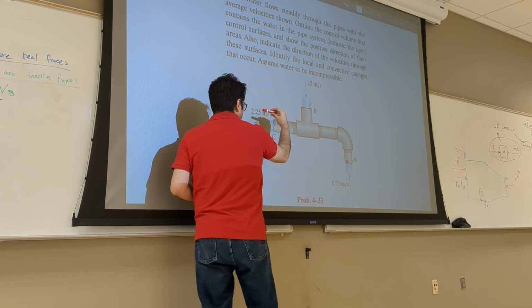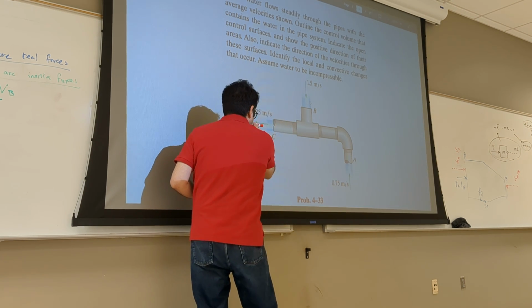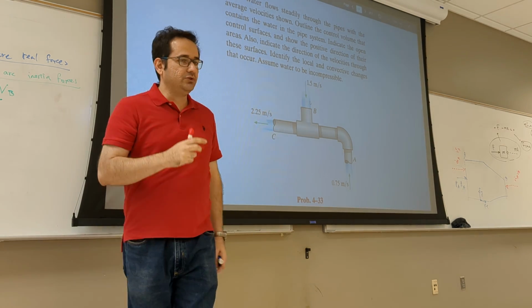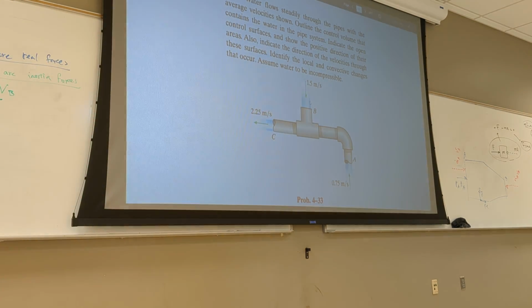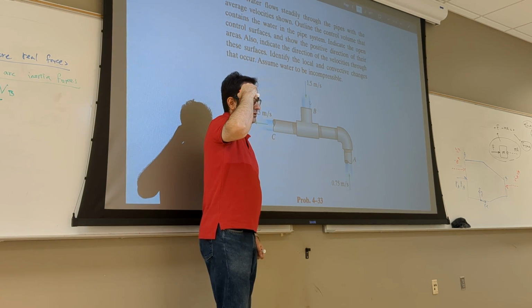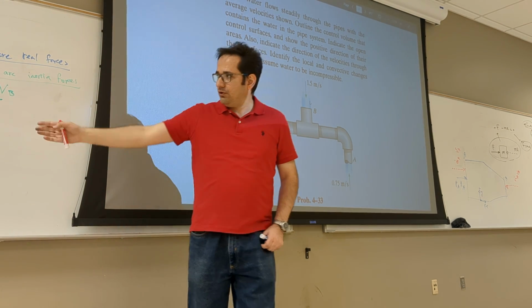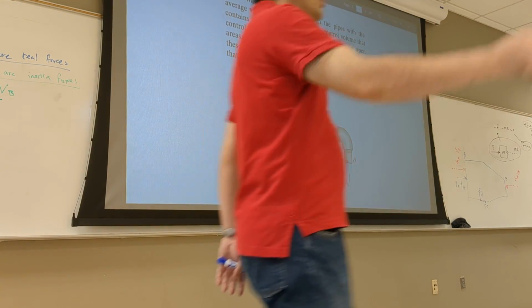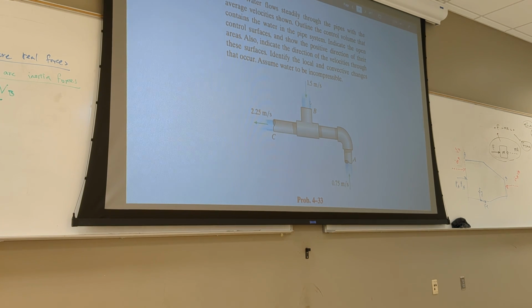Now if you put it on the FBD, you just leave the sign. So you dash, dash, dash, dash. The inertial load, when you submit the quiz, must be represented with dashed lines. If you don't put dashes, you get confused. That's a real load. In fact, when you come to vector statics, it doesn't matter if it's real or inertial, because you just sum them up with the same convention.